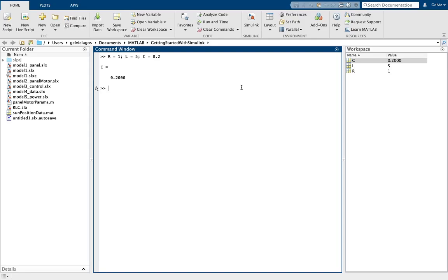Now, the first thing that we will do here is to convert the linear model, our model a while ago, the RLC, to a state space model. So state space model is denoted by A, B, C, and D. These are the variables that we will be using for our state space. Now this is A, B, C, D is equal to, by the way, we can eliminate this comma, just put a space here, and then put linmod.